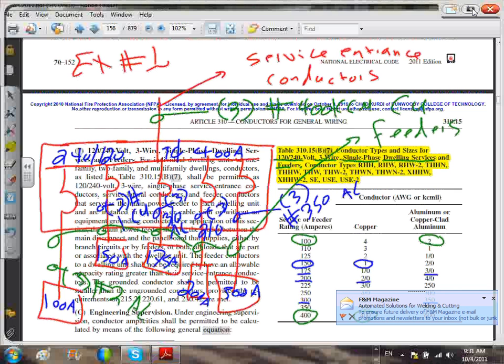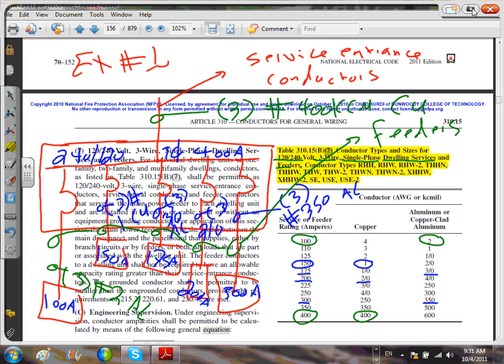Yes, sir. You use different kinds of conductors. Why did I use aluminum or copper? Just because of the exercise. You can use either aluminum or copper. Aluminum is cheaper. Non-engineered projects tend to use more aluminum because it's cheaper, lighter, and easy to work with. Copper is more expensive, heavier, and safer though. If it's an engineered job, most likely it will be a copper job.